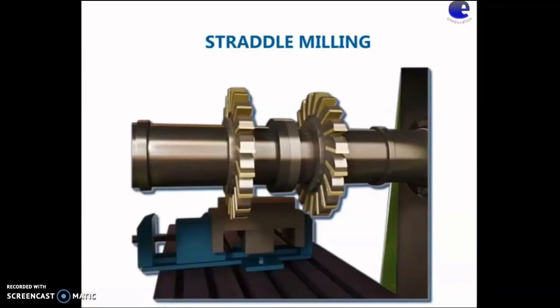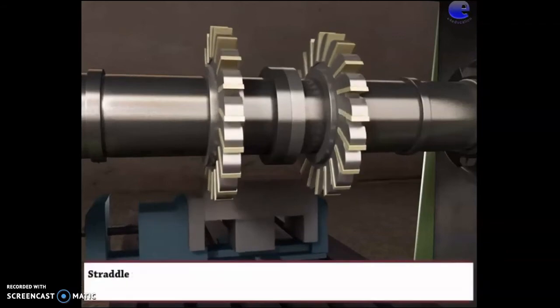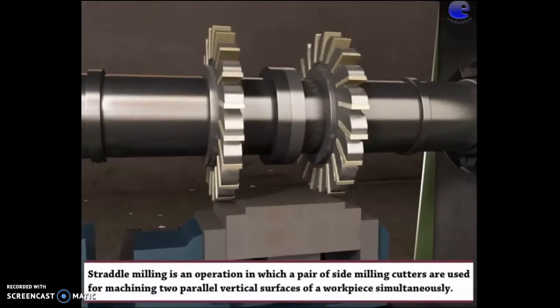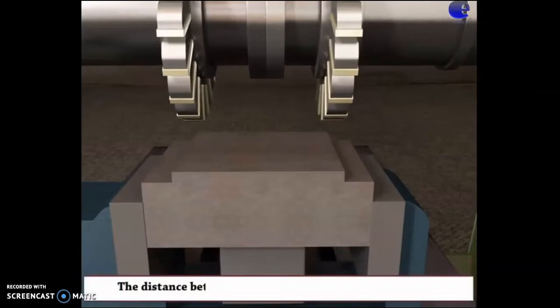Next, straddle milling. Here is a workpiece, side milling cutters, arbor, machine vice. Straddle milling is an operation in which a pair of side milling cutters are used for machining two parallel vertical surfaces of the workpiece simultaneously. The distance between the cutters is adjusted by the spacers.